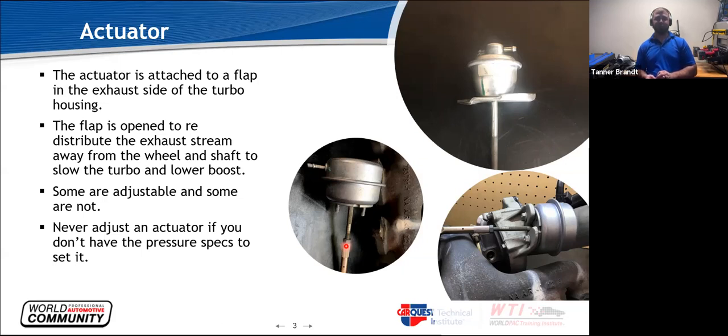I got called out to see why it was misfiring, and it was misfiring because they put the same turbocharger back on and blew up the second motor. So it's a very simple component, causes really catastrophic failures. So keep that in mind. The electronic ones aren't really adjustable, at least to the everyday Joe without tuning software. So that's not as big of a problem on that.